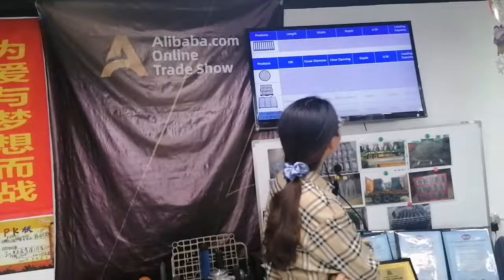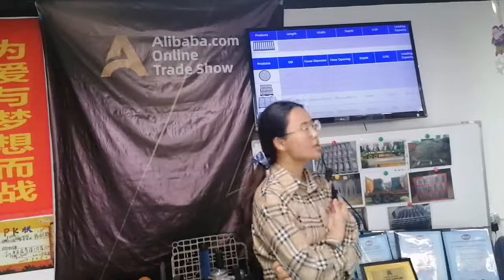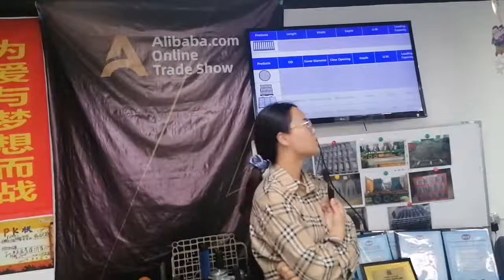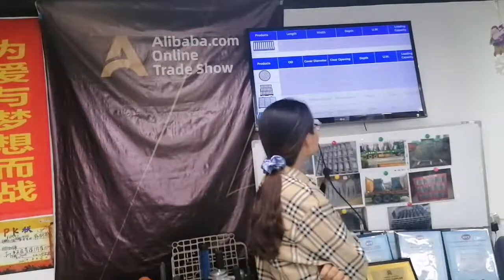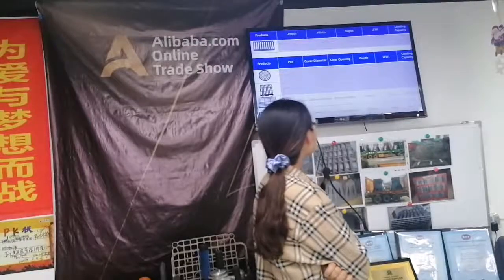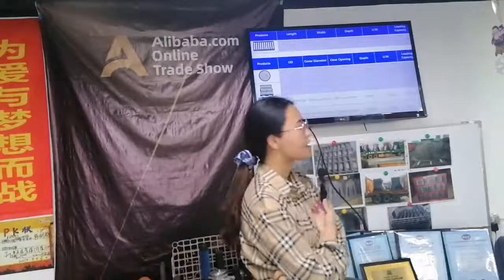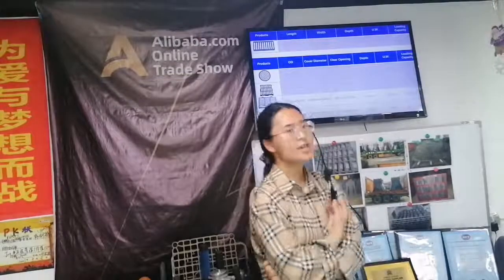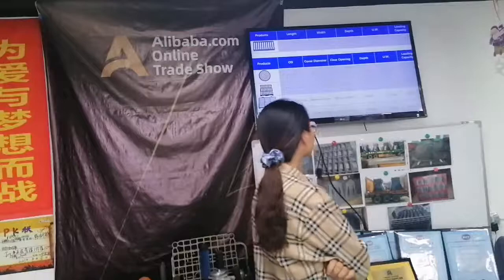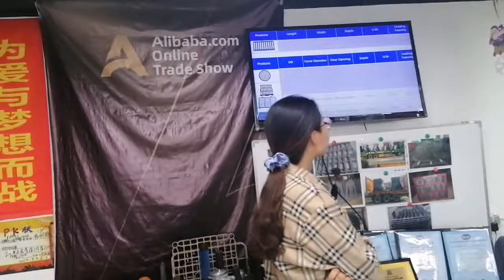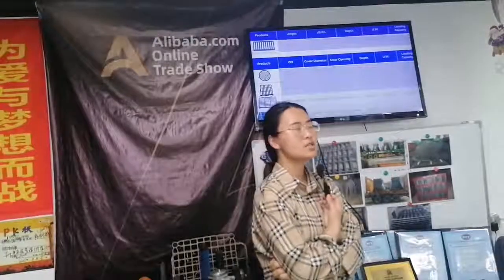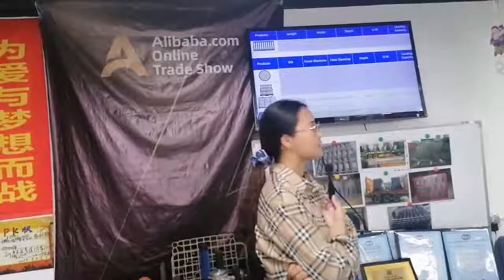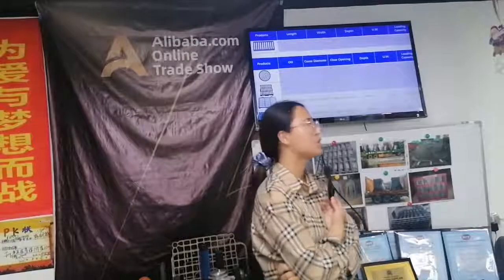The third one. For this one, the bearing capacity is about 25 tons, and the length is 630 millimeters. The width is 465 millimeters. The depth for this one is 40 millimeters. The unit weight is about 23.5 kilograms.